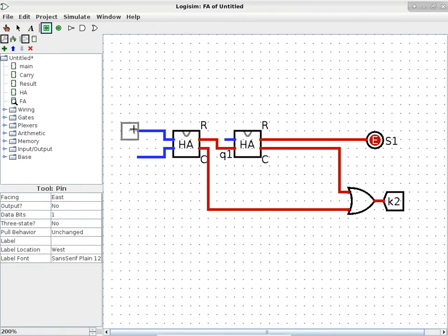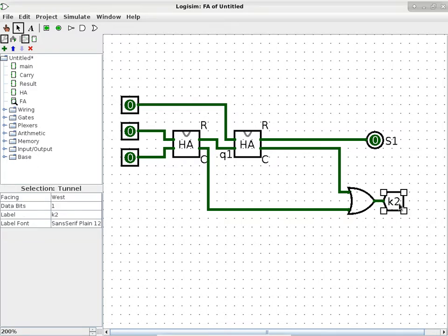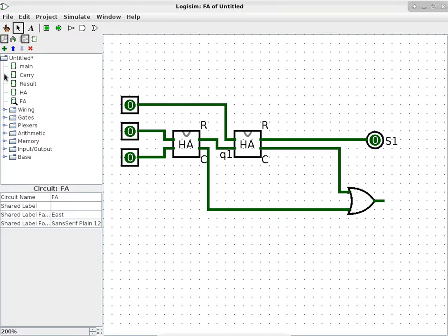We can just go ahead and specify the input pins for these two. Oh, what about this wire here? It is supposed to be the carry from the previous column. Okay. So we need one more input in this case. Okay. What about this one here? This is an output, but it's not going to an output pin. Maybe we should change this to an output pin.